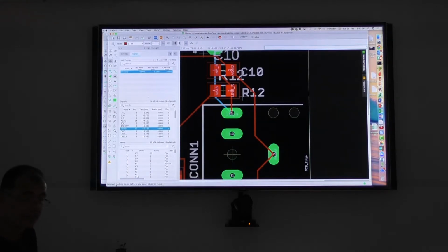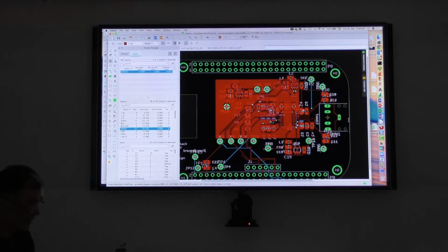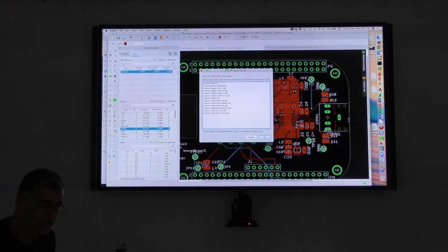And now the last step, I save it, and then I just want to show you, you could simply use the board file now, send it to the board manufacturer, or you create your manufacturing data by yourself. Therefore we have 2 tools. It's one tool, it's the CAM processor, but we have 2 ways to use it. There's the quick one, it's generate CAM data. I click onto this. Eagle tells me I will create all these files here.